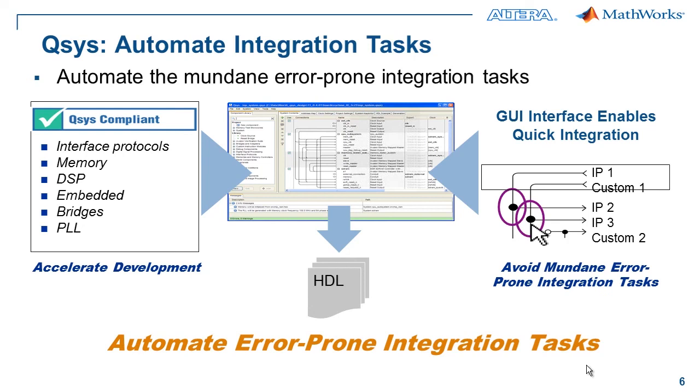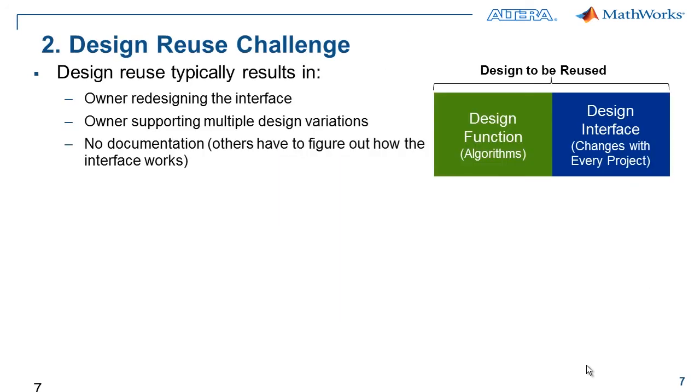Now let's look at how Qsys can help with your glue logic. First of all, instead of connecting hundreds of signals and buses between your multiple design blocks, we can use Qsys to do the integration work for us. Qsys provides an intuitive GUI interface that allows you to make connections between different blocks, effectively connecting many signals and buses together with a single mouse click. After you've described the connections between your design blocks, Qsys will automatically generate the interconnect for you and the interconnect HDL.